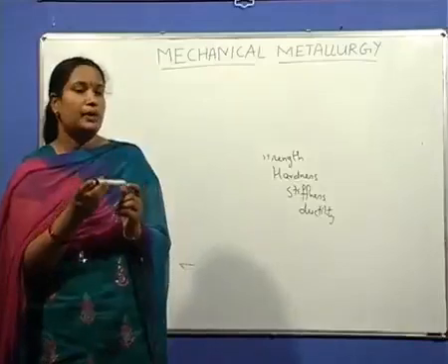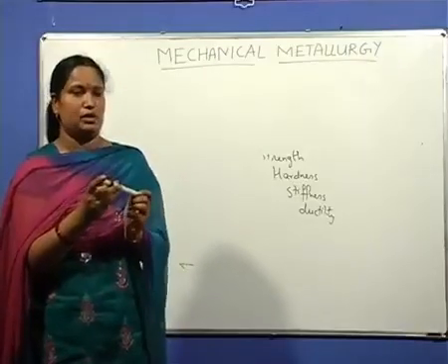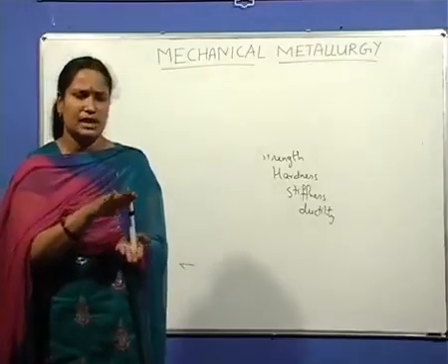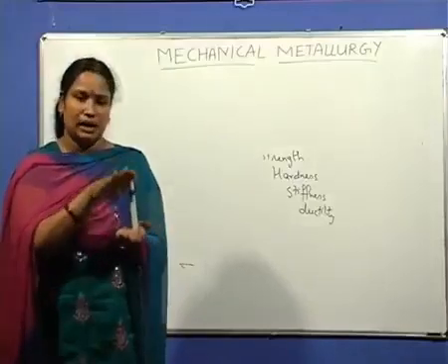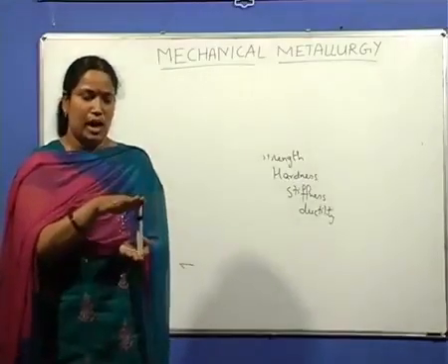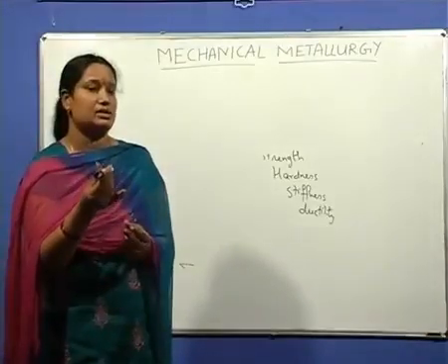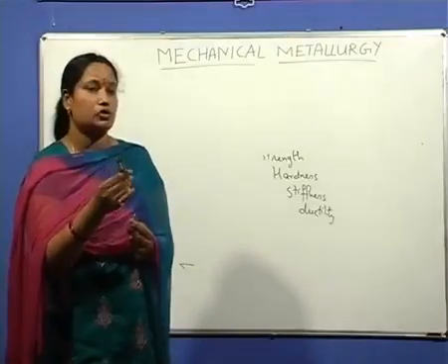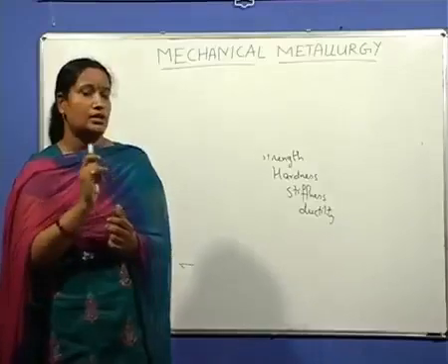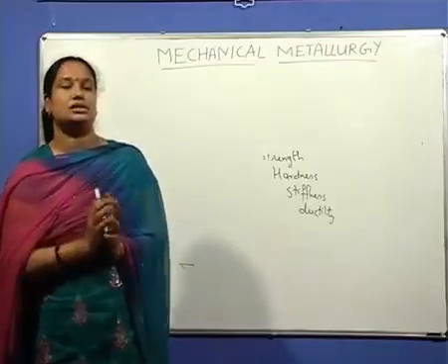There is no permanent change in the shape. The material only deforms elastically upon the application of load. As soon as the load is removed, the material regains its original shape prior to the application of load. This is known as elastic deformation.